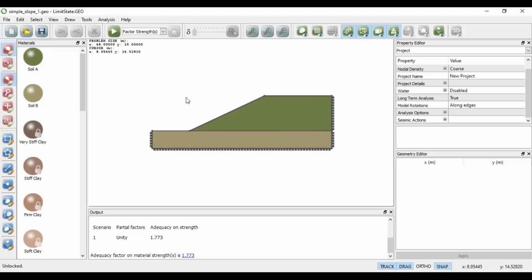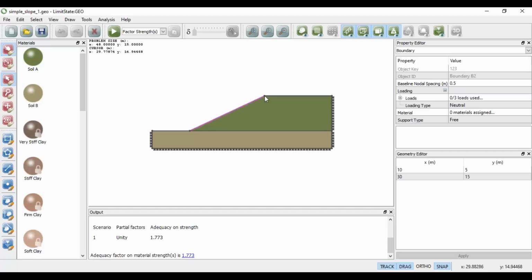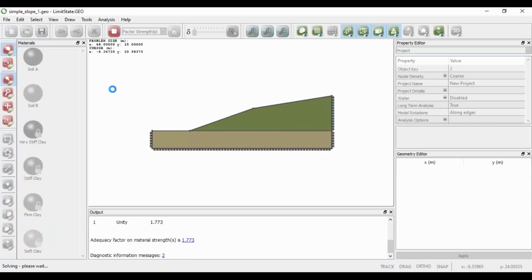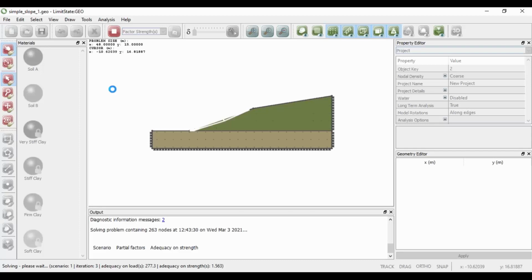That is essentially the core use of the software. It's very simple to get that solution. You don't have to preset entry and exit points or choose a solution type. It just goes straight there. But you've also got the flexibility to experiment. So, for example, I can change the gradient of the slope just by dragging and dropping and resolve, and it will give me a different failure mechanism. And you can see this time it's just, I think it will end up involving the base soil.